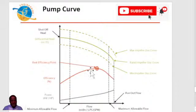So you can see your best efficiency point flow rate, because you cannot always be running your pump there because of the variations in your process requirement. So your flow rate cannot be fixed. However, the OEM must furnish you the minimum allowable flow, and it has to furnish you the maximum allowable flow. By the time we look at some of the basic design conditions as per API 610, you will see the margin in terms of percentage that has to be between your best efficiency point flow rate and your maximum allowable flow, or your preferred operating region.